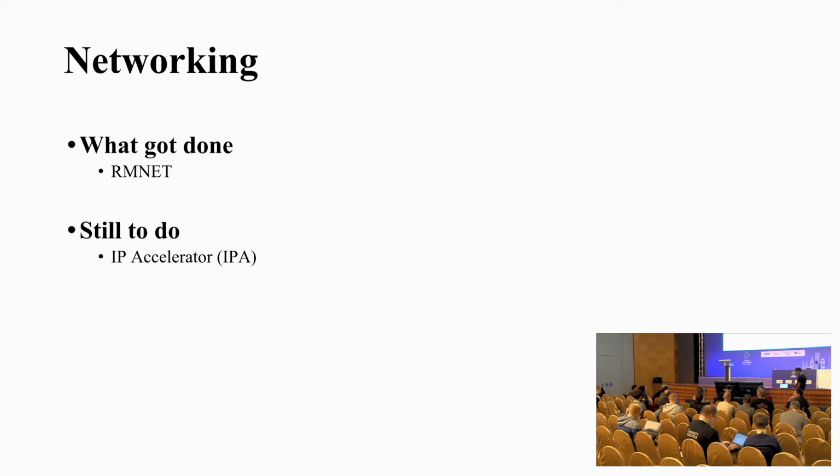So in the remoteproc drivers, I have an extension to this problem. Right now I'm memory mapping RAM, copying the firmware in there, and then we jump to TrustZone, and that will kick off the coprocessor executing that firmware. And we're just leaving it like that. If for some reason the app CPU would touch that memory, we get a system restart.